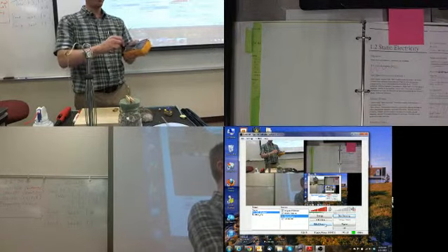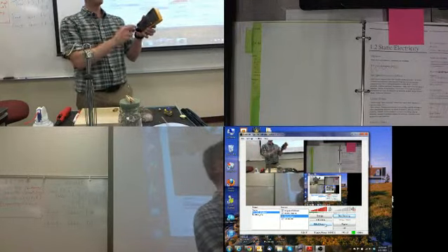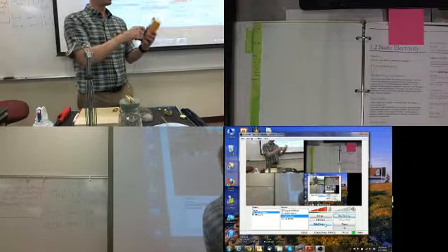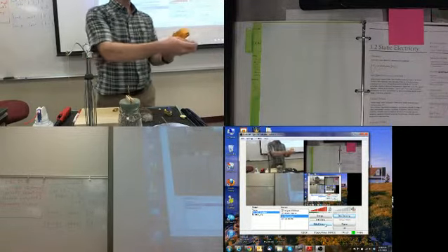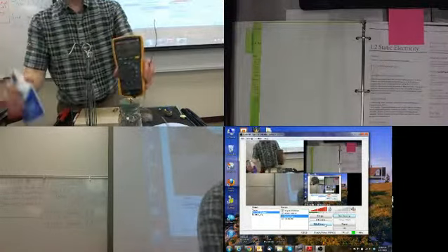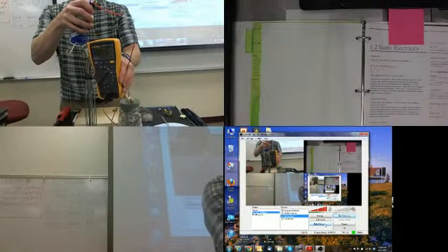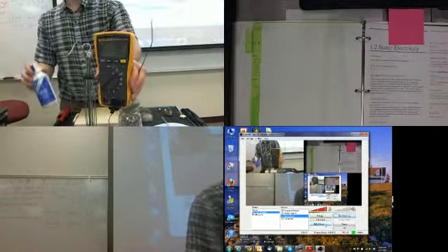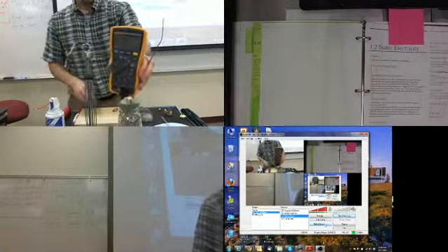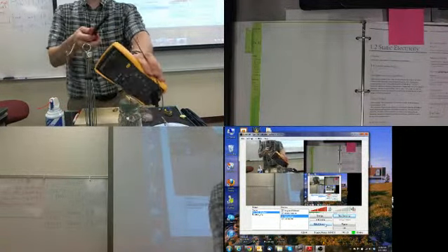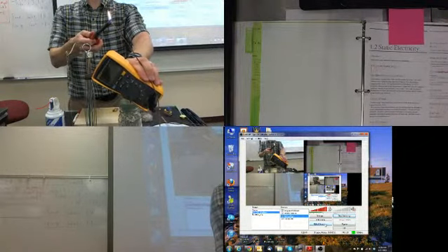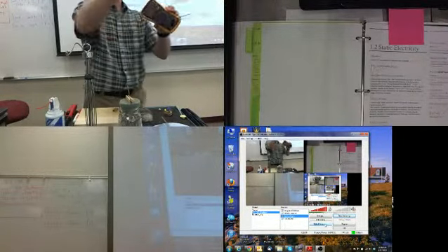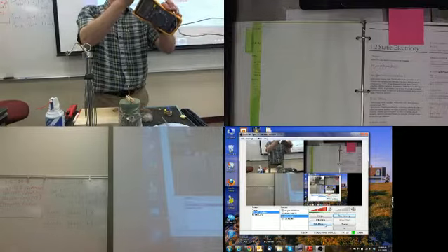That's all this is. There's no magic inside of here. Two wires with a different type of metal welded to the end. And if you can see the voltmeter here, hopefully something will happen. This is just cold air. What does it say on there? Minus 0.003. Now if I heat it up, what does it say? Going positive, 5, 6. So that's because the rest of this is room temperature. Now you're causing a temperature differential.